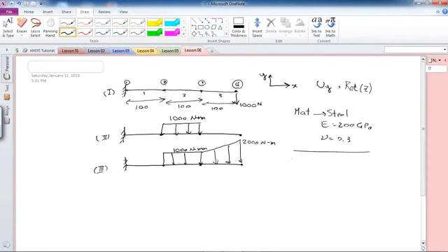And the element that I'm going to pick in order to do this analysis is going to be beam 3 with cross-section area of 12 times 12. So basically it's going to be square, of 12 units by 12 units, which means my area moment of inertia is going to be 12 to the 3, as we had measured or calculated this similar thing in lesson 1. So with this, we can go to Ansys and do the analysis.